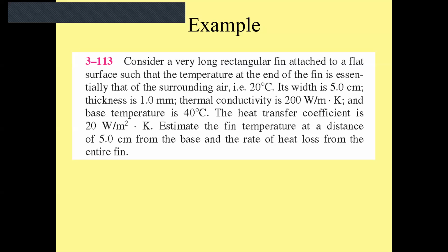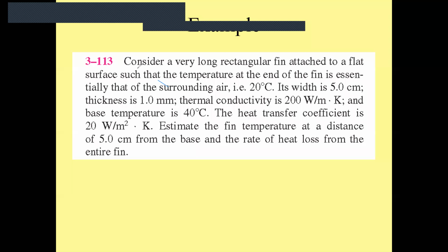It says here that the fin tip is at the same temperature as the surrounding air. So this means the fin is very long. For example, you have this fin, and then you can plot the temperature profile.